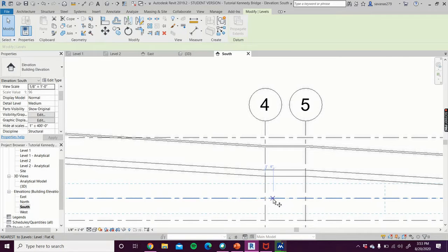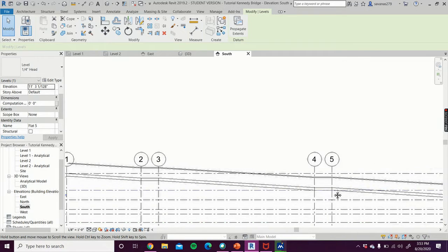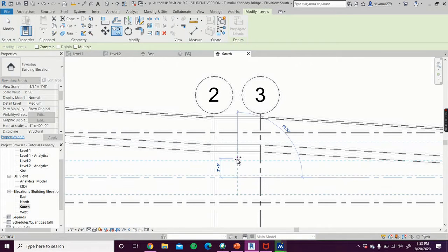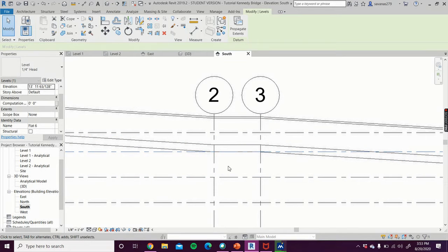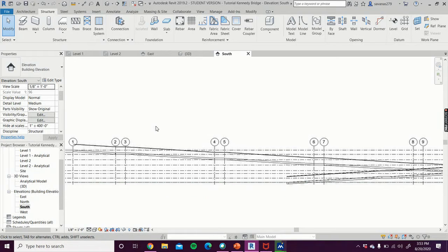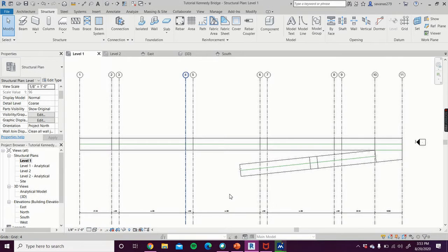I'm doing this because otherwise I would have to type in the actual dimension for each top of the column. So this will be easier instead of having to search for the dimension every time. And we can always hide these when we create our sheets, because it might look a little messy to have all of these there. We'll just add the dimensions. Okay, that's done.